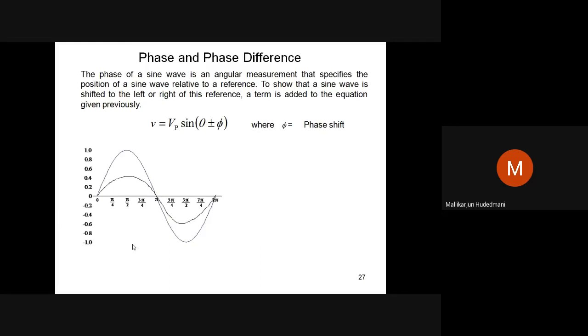If the circuit is resistive, current follows the voltage, nothing but an in phase relationship. If the circuit is inductive, current trails behind the applied voltage, we say lagging. If the circuit is capacitive, current leads ahead of the applied voltage.